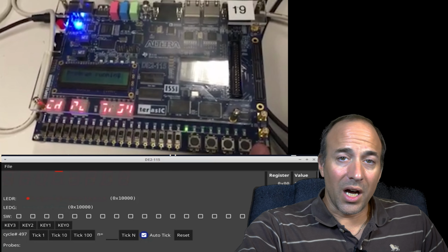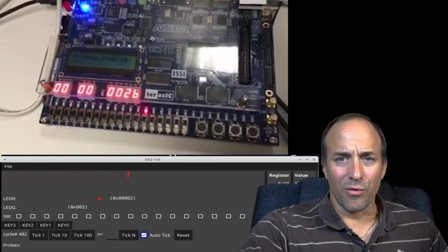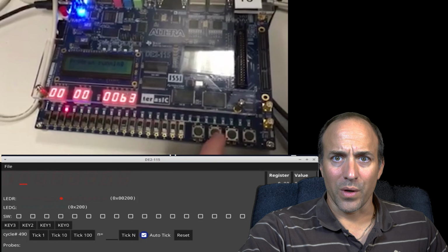The virtual DE2-115 adds in software that creates a graphical user interface that Charles developed in Golang, as well as a set of makefiles that links the output of Verilator with the graphical software that Charles wrote that creates a graphical virtual DE2 on your screen.